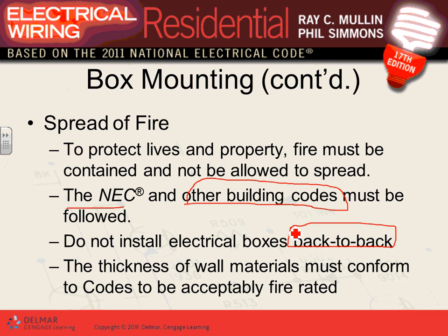When it comes to the spread of fire, that's a big thing, guys. Thickness of the wall material must conform to the fire-rated wall. When you guys graduate from here, you're going to hear a 1 hour fire rated wall, 2 hour, 3 hour fire rated wall. That's how long it will take the fire to move from this location to the other location. 1 hour typically sheetrock, 2 hours or so double sheetrock the area.